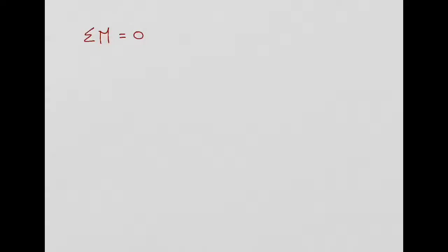In fact, we are not going to use exactly this equation. We are going to say the summation of moments produced by the internal shear flows needs to be equal to the summation of moments produced by the external force. I can write it like this. If you want, you can send this to the left-hand side, and then you have this equation.